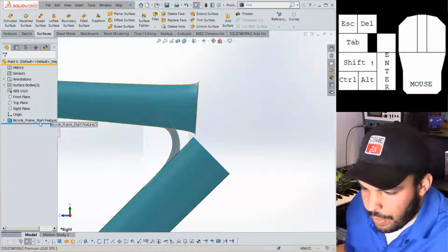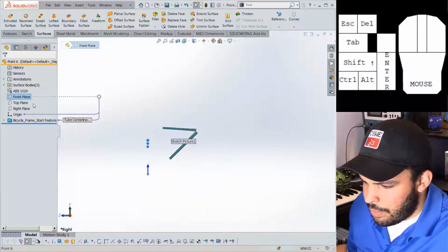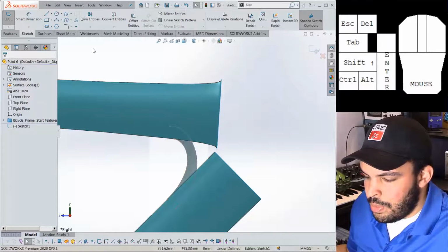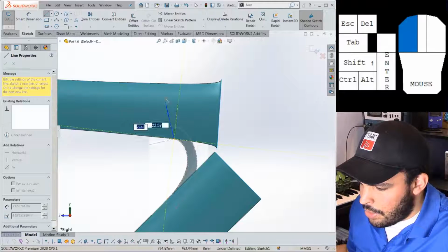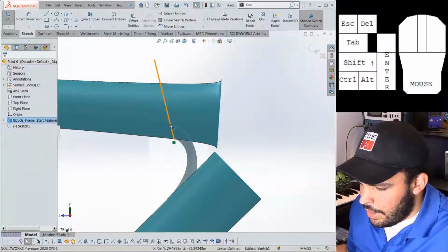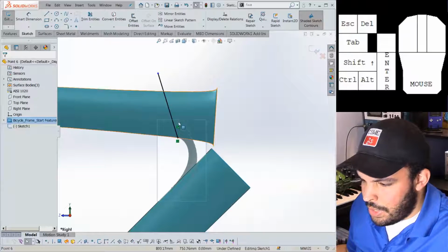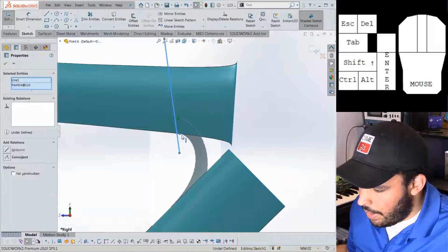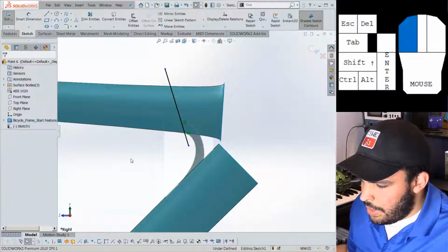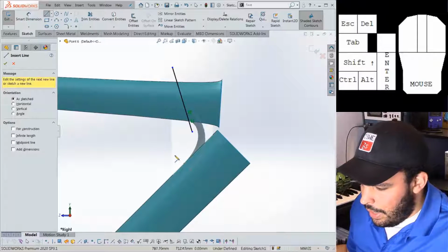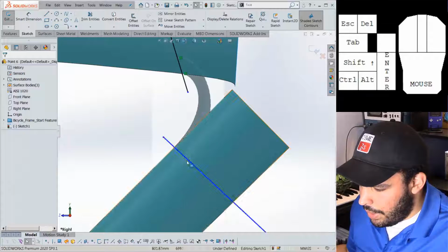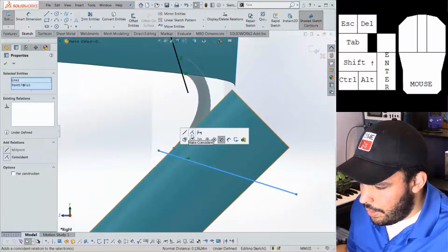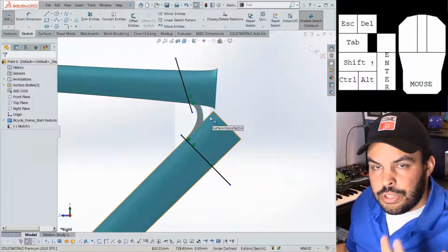So let's just go for it, right? I'm going to sketch, let's see, is this the front plane or the right plane? All right, sketch on the right plane. And I want to trim these two members down, so reasonably, I may start here and go out like that, and have that be coincident, so that will lock it at a particular angle. And actually, it would be better if I overextend it a little bit. Coincident, there we go. And a line similarly over here. So coincident, and here coincident. All right, so let's just roll with this for right now.